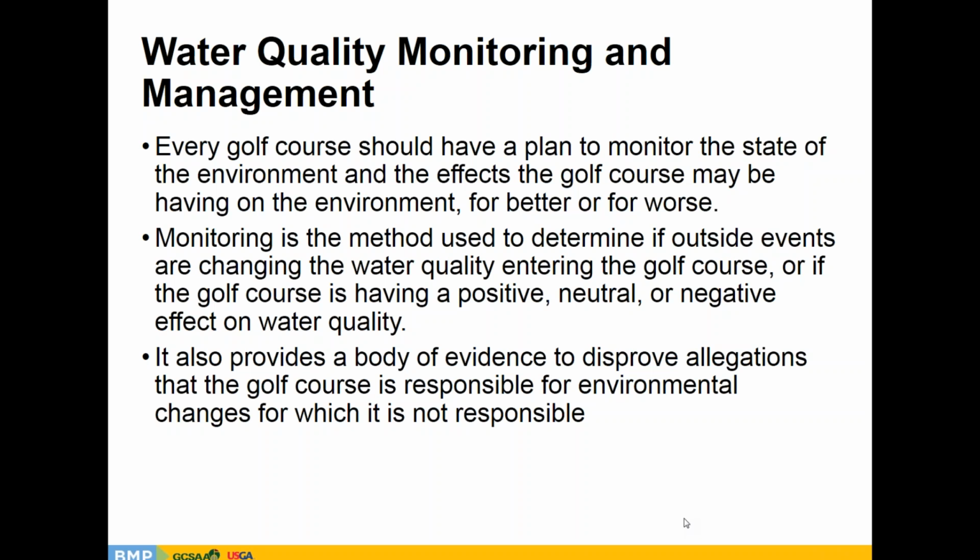I was involved in a golf course here in Florida where, through a Lake Watch program, the water body adjacent to the golf course, not on the golf course, had extremely high levels of phosphorus in the water. The golf course superintendent was able to come in and show evidence, through his fertilizer practices and his record keeping, that he had applied only negligible amounts of phosphorus to that golf course over the last 5 or 6 years. We were also able to find some water quality monitoring data where that particular water body had been monitored for years, and the phosphorus levels had always been elevated in that water body.